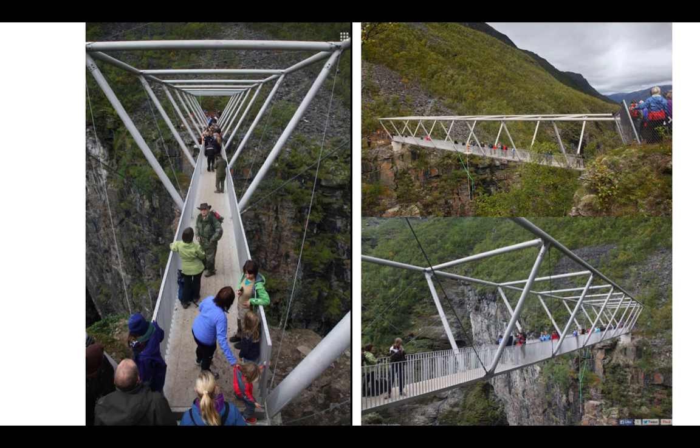You may have noticed that the deck was actually installed after the structure was brought in, right? So to save weight for the helicopter. But you'll also notice that even though there's kind of precious little, quote-unquote, architecture here, it's an architecturally dramatic structure, right? Those constraints have made the bridge really, really elegant. They've forced decisions about structural geometry. Notice all the triangles. They've forced decisions about appropriate materials to appropriate behaviors.